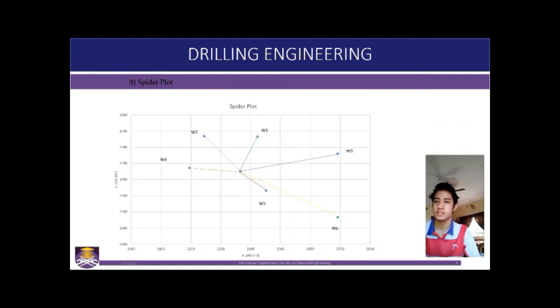As can be seen in this figure, the top view of the location of the wells shows that the wells were positioned accordingly in the target production areas. It clearly shows the location of the production wells and injection wells in case 1. Water injection was employed to push the oil towards the production well. This is because the reservoir itself is experiencing gas and solution gas drive. Thus, if gas injection is used, it will not affect the change of pressure in the reservoir. This will only increase the amount of gas in the reservoir, which would need to be overcome as no gas production was done for this field.